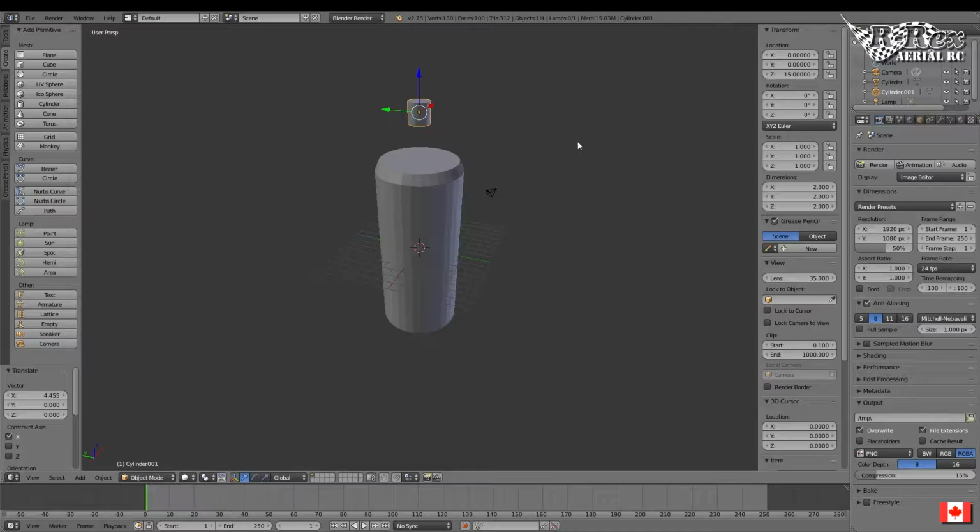Okay. Now we want to set this for, let's say, the shaft. Remember, this is mostly just for clearance issues, so I'm going to go 1 by 1. So this is a 1 millimeter shaft, and because I measured, let's say, 4, I'm going to go to 5.